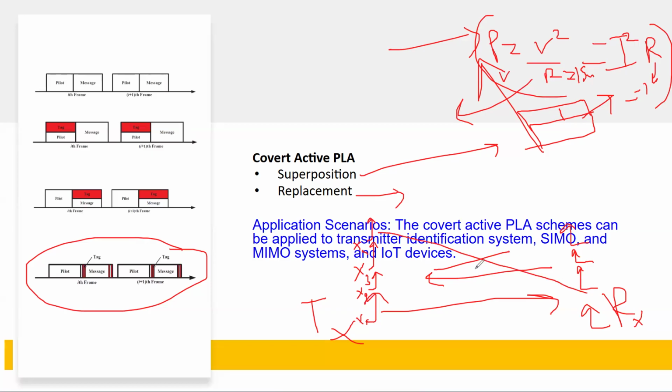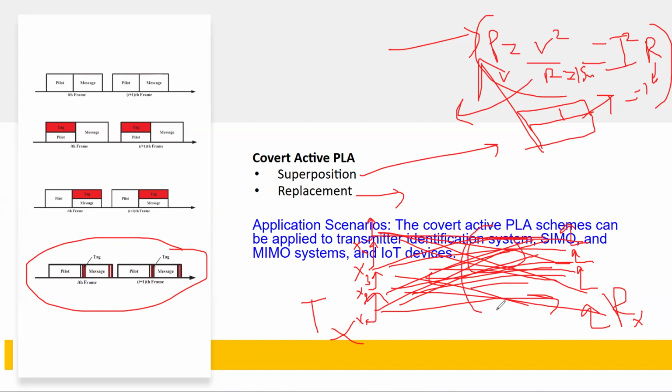In this case, all the antennas receive. Each antenna here is transmitting to all the antennas at the receiver. Same here. Same with this. The signal goes to all the receiver antennas, and the same with this. So you see these interconnection lines. This causes inter-antenna interference. And the receiver's job is to be able to handle that, to remove these interference links.